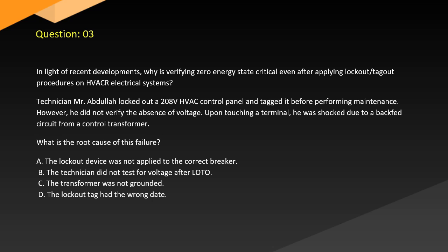What is the root cause of this failure? A. The lockout device was not applied to the correct breaker. B. The technician did not test for voltage after lockout. C. The transformer was not grounded. D. A lockout tag had the wrong date.